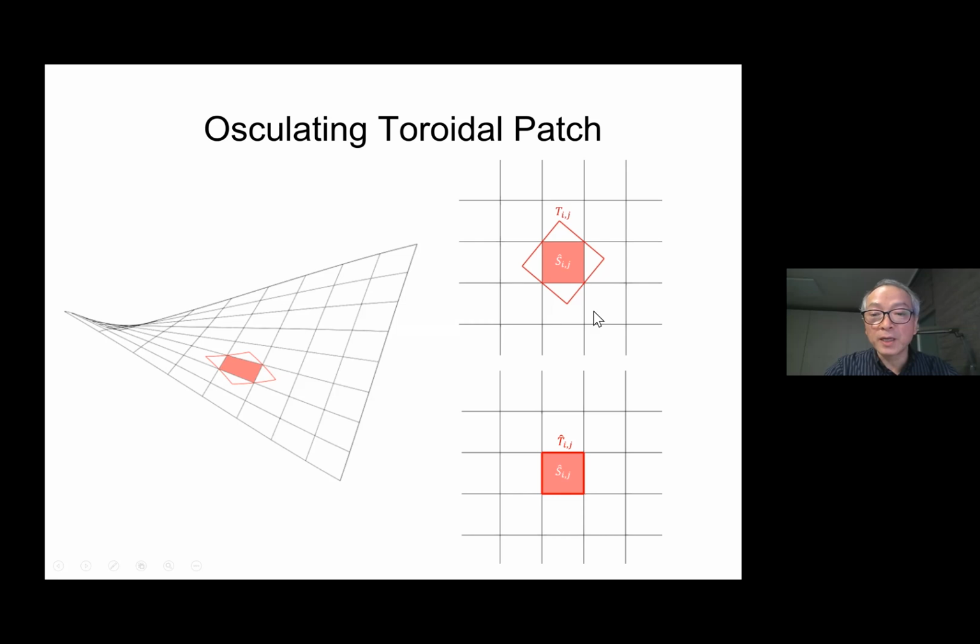Because of the different parameter direction and principal direction, the osculating torus may have a different shape like that, but we can actually trim this part and that part. And then we can make a trimmed osculating torus and the original small surface patch having about the same position and about the same normal direction at their corresponding parameter locations. You can do that for the majority of surface parts except non-degenerate, non-regular points. At non-regular points, you cannot really do that. So we will come back to this issue shortly.